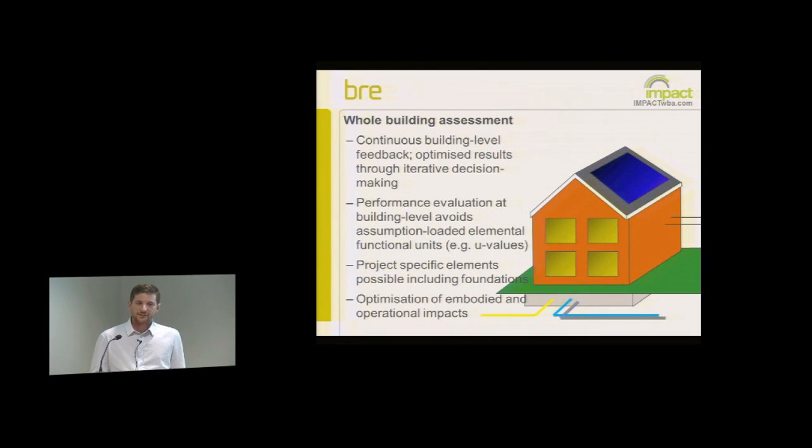The other benefit is that through whole building assessment, the comparison is really the building type and how much of that you're providing. So for example, for offices, it would be how many metres of net internal area. So you can avoid the need, with elements like an external wall, to ask what does that external wall do, what's its performance, which normally gets boiled down to very basic functions, things like the U value. So it just avoids and tidies up the need to do any of these things.